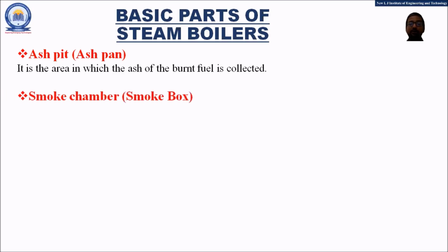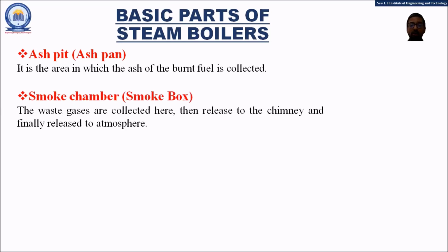The next important component is the smoke chamber, also known as the smoke box. The hot gases which are generated in the furnace, after they give their heat to the water, now have reduced heat energy, so there is no use of the hot gases. Hence they are now considered as the flue gases or the waste gases. So it is very necessary to remove the flue gases.